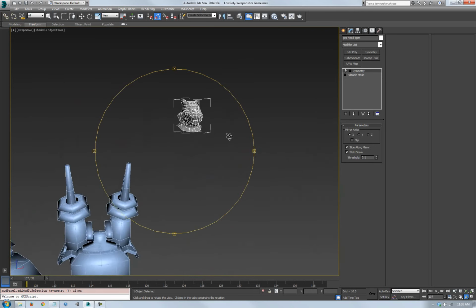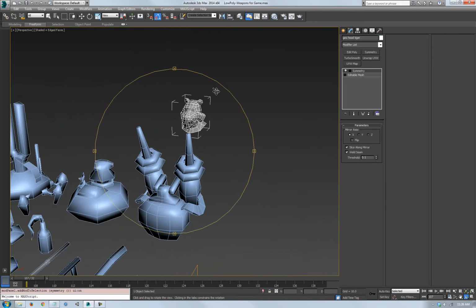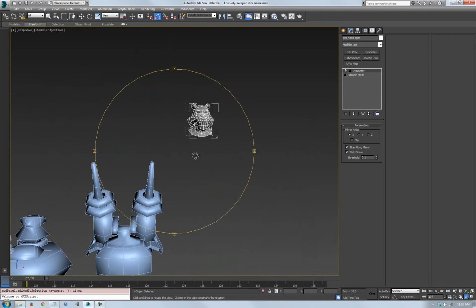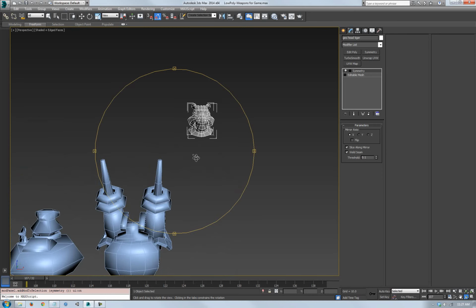Now, you're still going to have to go in and tweak and adjust and modify, but if I already had this head unwrapped, the way the UV system works is that each vertex has its own unique identifier, or an index. I'm not exactly sure how it handles it under the hood, but each vertex is like vertex number 1, or vertex number 2, or vertex number 3, and it's at XYZ coordinates. It's connected to vertex such and such. But when it comes to the UVs, each vertex has an index, and this vertex is at U and V on the texture coordinates, and U and V is basically like X and Y. It's simple planar. So if you don't cut out or add too much geometry to something that's already been unwrapped, you can still, for the most part, see some of the source UVs.